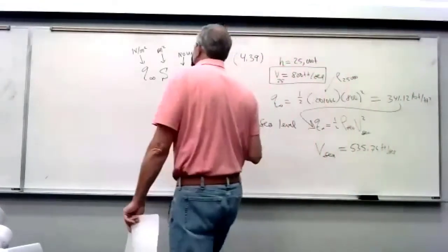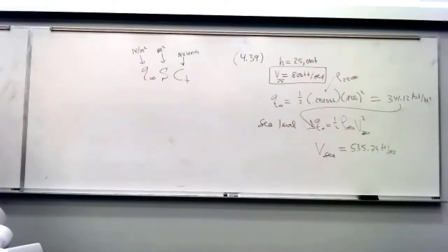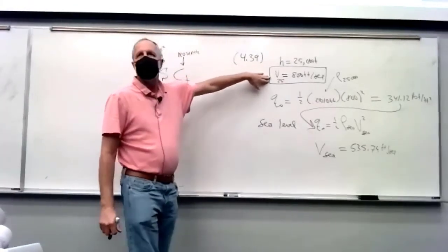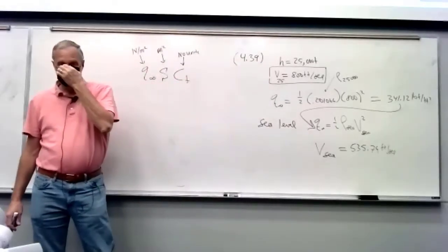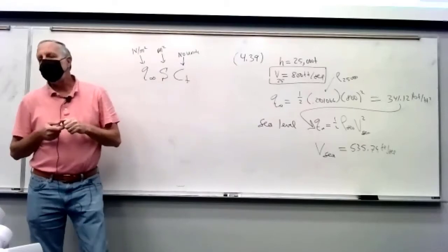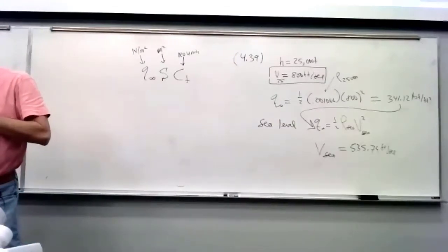It's important, though, because they'll talk about airplanes going faster at altitude than they can at sea level. If you measure a Mach number, it's because of two reasons. One, the temperature goes down as you go up in altitude, so the speed for Mach 1 at altitude is lower. But the other reason is that the density is lower at altitude, so there's less dynamic pressure and you get less drag at altitude as well. So you need less thrust to go even slower and still go Mach 1 at altitude. If you go really high, you can go Mach 6, but there's hardly any air up there.